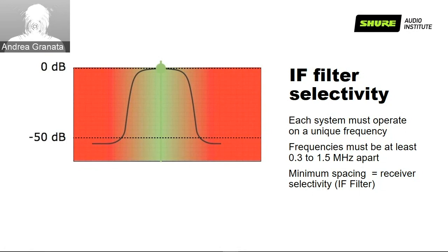But if my device is a wideband device, like 150 megahertz, my selectivity won't be that efficient, and I cannot have a track tuning filter with a span of 15 or 20 megahertz capable of tuning in a wide range. This is why for analog systems there is always a certain compromise to be taken between selectivity of the filter itself and the tuning range of the device.